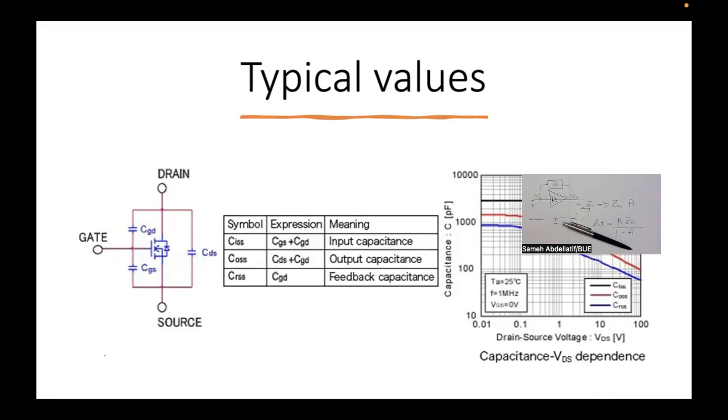Herein, your parasitic capacitance will be in the same range as your load capacitance. And in this case, you will face a problem because your parasitic capacitance will act toward changing your circuit design elements and changing your frequency response and resonance frequency.